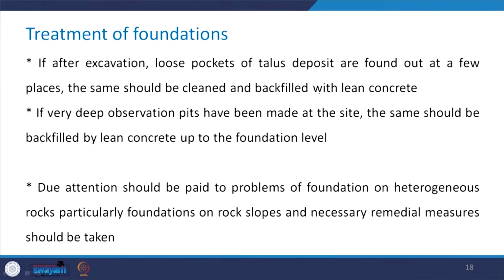Now, if after the excavation, say loose pockets of talus deposit are found at a few places, these should be cleaned and backfilled with lean concrete. In case very deep observation pits have been made at the site, these also should be backfilled with lean concrete up to the foundation level.